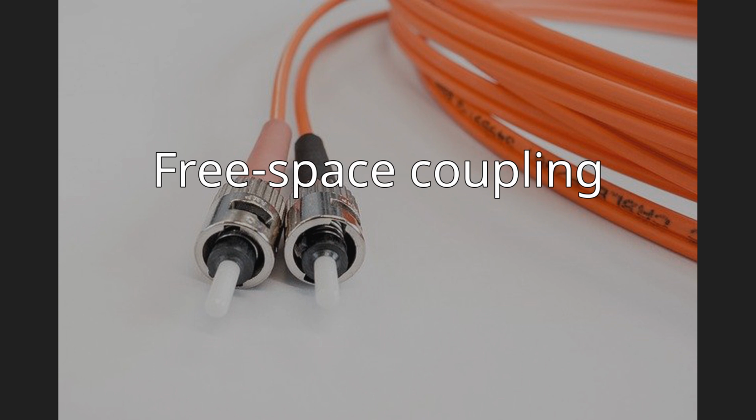In this case, a tapered or lensed fiber is used to match the fiber mode field distribution to that of the other element. The lens on the end of the fiber can be formed using polishing, laser cutting, or fusion splicing. In a laboratory environment, a bare fiber end is coupled using a fiber launch system, which uses a microscope objective lens to focus the light down to a fine point. A precision translation stage micropositioning table is used to move the lens, fiber, or device to allow the coupling efficiency to be optimized. Fibers with a connector on the end make this process much simpler.